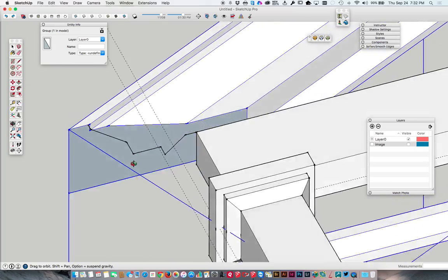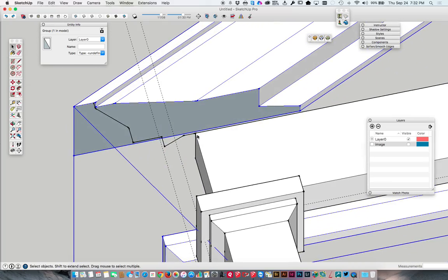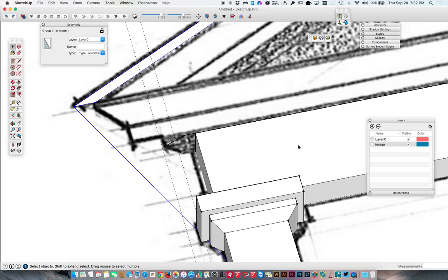So you have to be careful because when you were drawing, you were snapping to things that are in 3D space. So you actually have to be very cautious of that. So I'm just going to undo that, undo, undo, undo, undo, and I'm going to make sure that I'm on a certain plane. Now to do that, my trick is I just create a plane. Now, even though this photo is on a plane, it's not geometry.